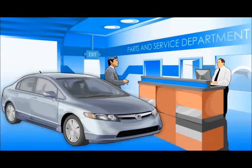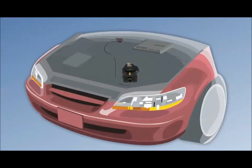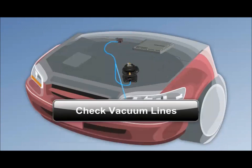If a vehicle with this type of mount arrives with a complaint of excessive vibration at idle, make sure the control system is working correctly. Confirm the PCM commands the solenoid on, check solenoid function, and inspect the vacuum lines for cracks or disconnection.